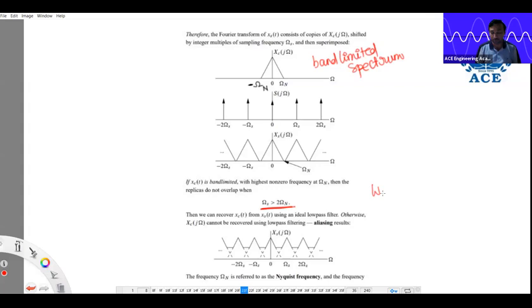How did we study this point in our discussion? In our sampling theorem, we studied that omega naught is greater than or equal to 2 times omega. But instead of omega, now we are using the ohm symbol for analog, without confusion. Omega for digital, ohm for analog. But undersampling leads to the aliasing problem. We know that undersampling leads to the aliasing problem.